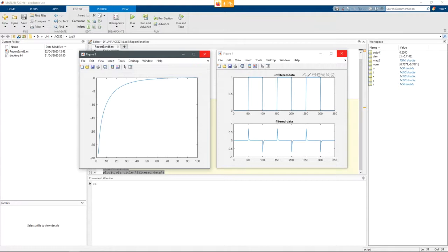And as you can see, what type of filter do you have now? This is a high pass filter. So we expect to see low frequencies getting attenuated and high frequencies being preserved. So as you can see, you still have some sharp edges in your signal after filtering, but the parts that were 1 have been removed. So the parts where the pulse is 1 have low frequency. But when we have a change from 0 to 1, we have high frequencies and they are still in the plot. Yeah, okay, that makes sense.